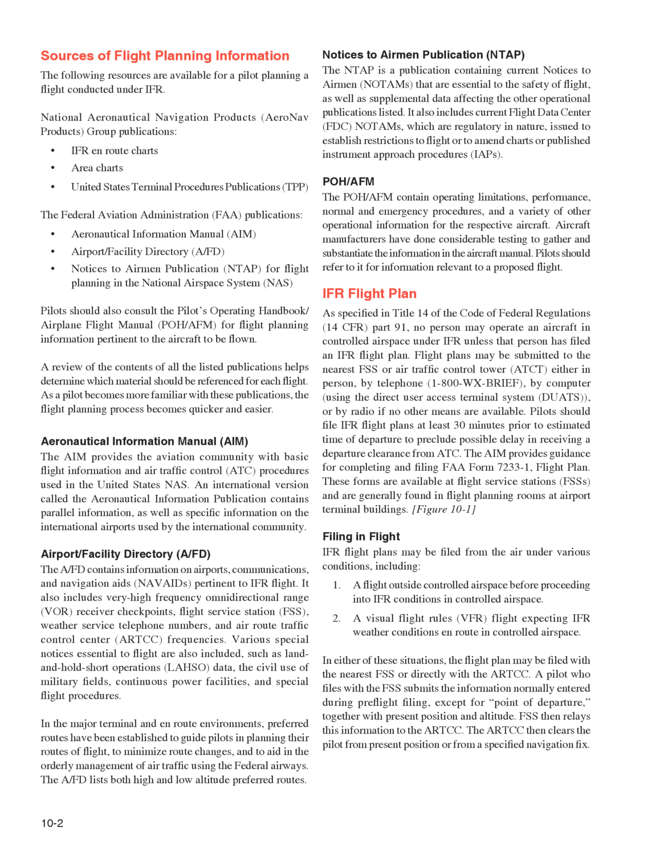A pilot who files with the FSS submits the information normally entered during preflight filing, except for point of departure, together with present position and altitude. FSS then relays this information to the ARTCC. The ARTCC then clears the pilot from present position or from a specified navigation fix.